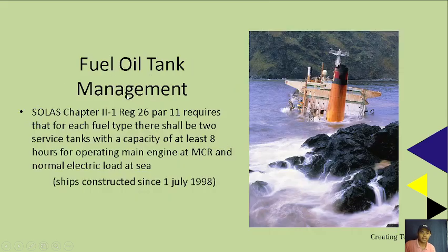Fuel oil tank management. SOLAS Chapter 2-1 Regulation 26 paragraph 11 requires that for each fuel type there shall be 2 service tanks with a capacity of at least 8 hours for operating the main engine at MCR and normal electric load at sea. These are for ships constructed since 1 July 1998 onwards.